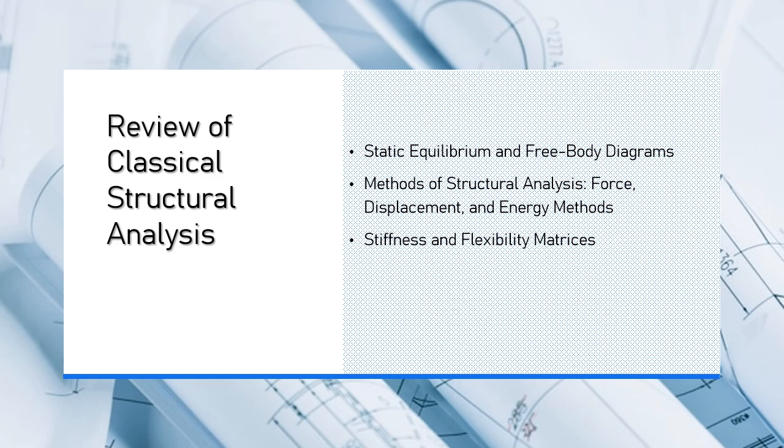2.2. Displacement methods. Displacement methods, also called stiffness methods, are based on the concept of solving for displacements, deflections, rather than forces. These methods are particularly useful for indeterminate structures and structures where the number of unknown displacements exceeds the available equilibrium equations.